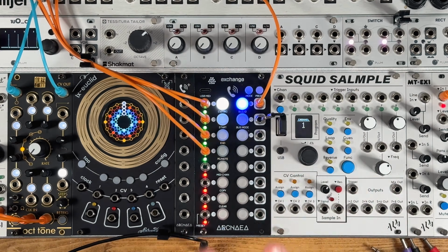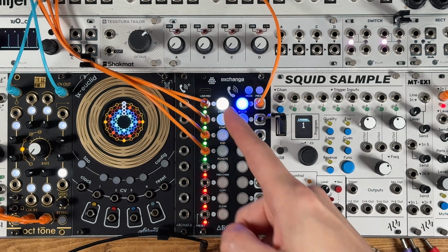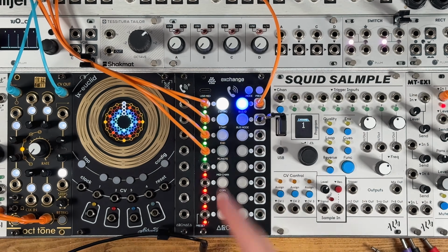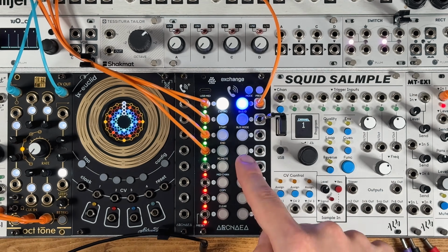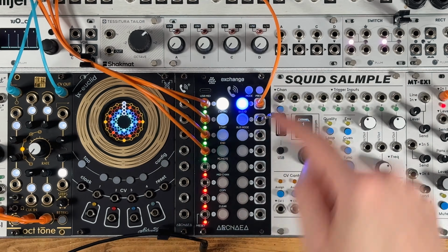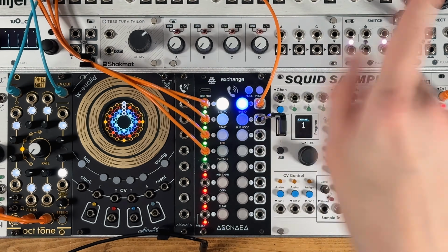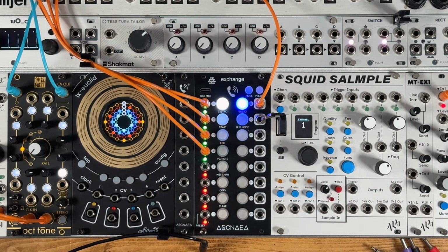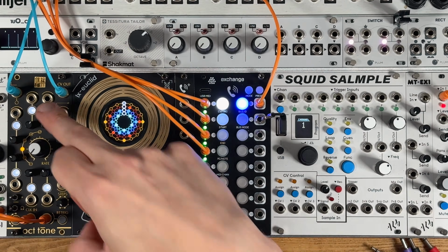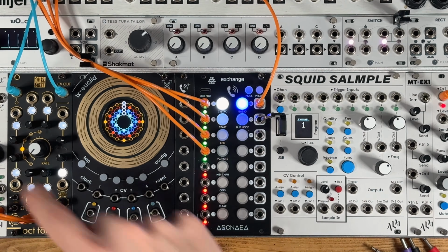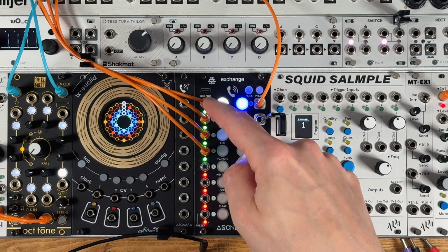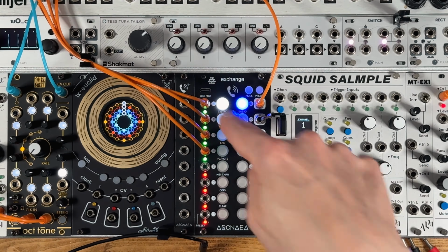So to demo this, I've got a classic sequential switch patch where we've got 4 outputs from an oscillator that's just off screen going into the first 4 inputs here on Exchange. And as I step through the presets in Bank 2, it will map them one at a time to this single output. The output's going to go through a filter and a VCA, and the oscillator is going to be driven by a sequence from the Octone here. So if I get that going, we're going to listen first of all to the triangle wave that's coming in on input 1 being routed through.